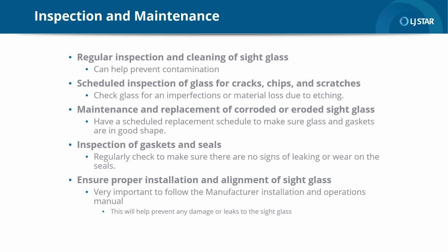So if you are replacing these components, you want to make sure that when you replace them, you clean the sealing surface fully. So many times you'll take the gasket and the glass out. The gasket may leave remnants on the counterbore where the glass fits. You want to make sure that you get all that removed so that it's a completely flat surface.